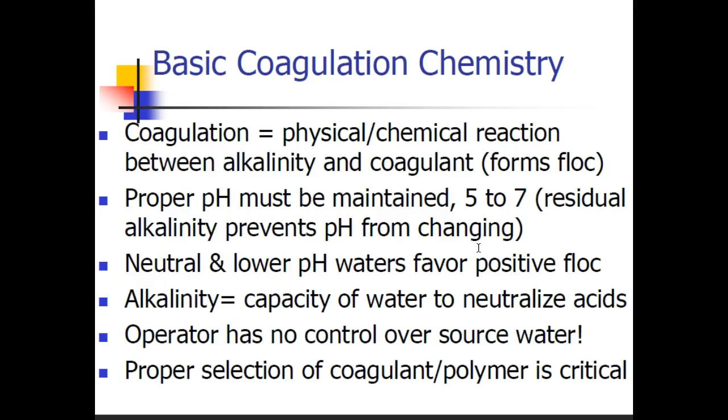I drove by New Maloney's yesterday, and with all these storms going, it looks like chocolate milk, let alone the fact that there's huge debris flows going. So we have all kinds of things, and an operator obviously has no control over that. The proper selection of a coagulant and polymer is critical.